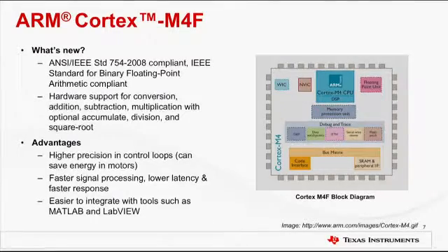The new Cortex M4 core has an IEEE 754 compliant single precision floating point unit with single instruction multiple data for 16-bit data types along with a 32x32 multiply accumulate with 64-bit result. The processor delivers exceptional power efficiency through an efficient instruction set, thanks to its extensively optimized design.